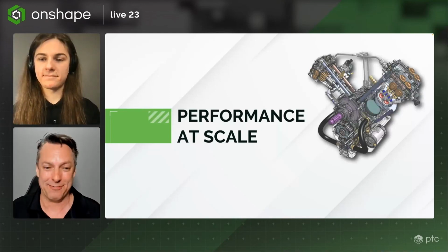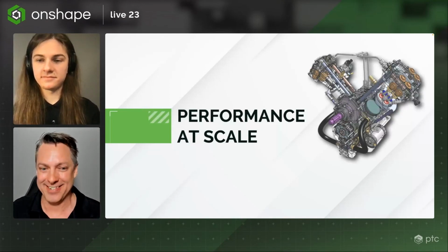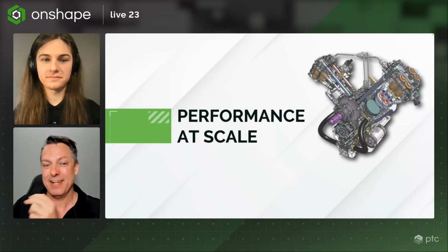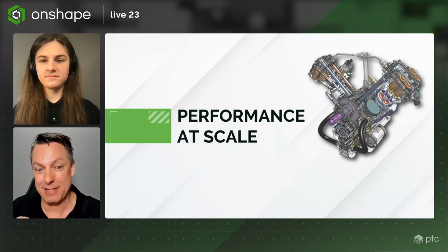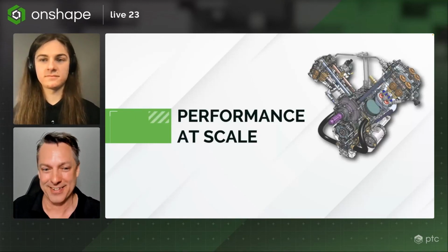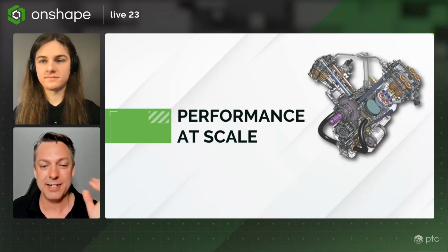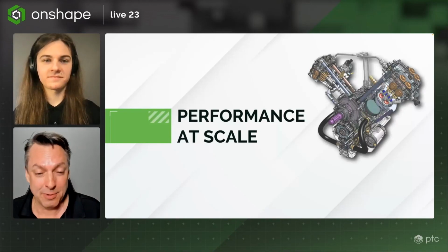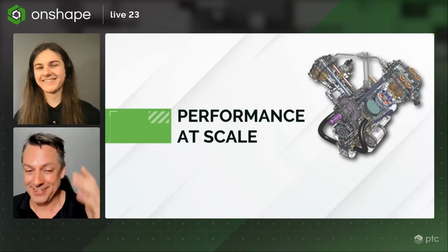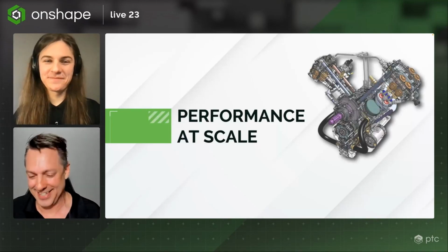I picked up another new one from you, which was in the layout sketches to put the mate connectors, because the validity of the assembly mates is now independent of the presence of other components. Love it, Ornis. Some great tips and tricks there from, I'm going to call you a world champion. You did win the competition and you were the only one using Onshape, so congratulations.